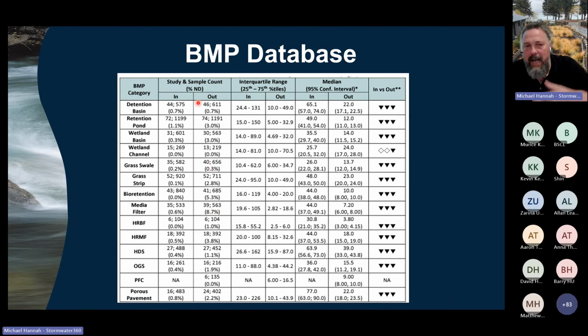As I said, this is a table out of it for dissolved zinc removal. It's really quite good because it tells you the quartile range. It's got your 25 percentile concentration in is 24 micrograms per litre and a 75% out. So you can kind of estimate percentage removals here, and the median value. I note they use median values because it's not quite a large enough data set.